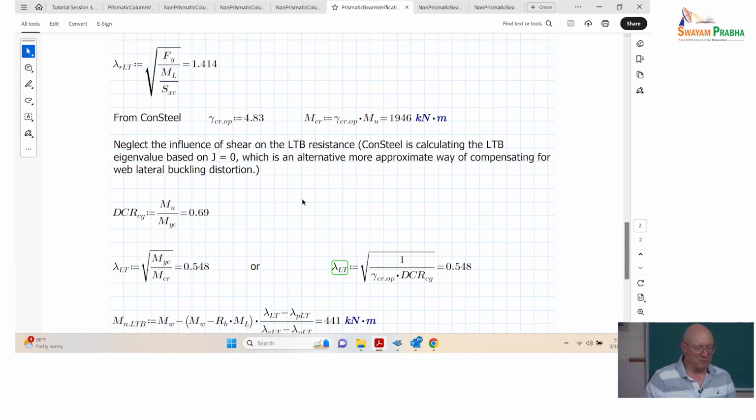Now, if you caught what I was showing you last Thursday night, or what I showed you a little bit yesterday with the flexural provisions that are moving forward, in the current AISC specification, if it's a slender web, we calculate lateral torsional buckling strengths taking J equal to 0. We don't account for any contribution from St. Venant torsion. I think AISC and the U.S. bridge standard are the only ones in the world that are doing that.